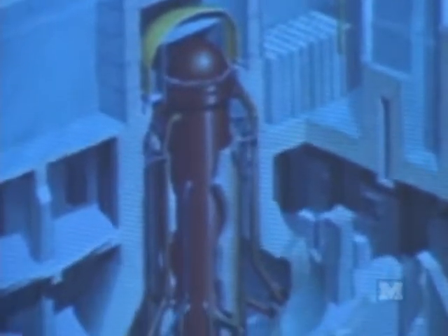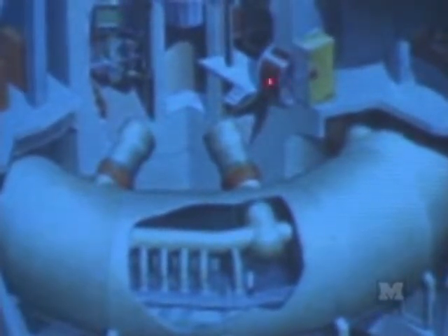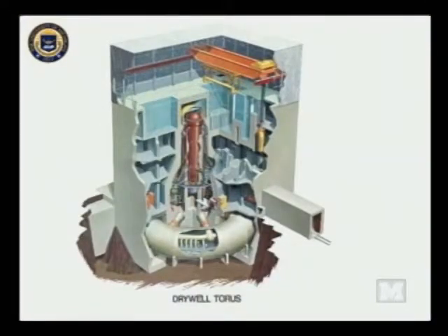And then connected to the light bulb-shaped dry well, the primary containment, is the suppression pool, which is connected through automatic depressurization system valves, several of them. The idea is when the pressure builds up in the reactor vessel, steam can be vented to the suppression pool, thereby relieving the pressure. And of course, the suppression pool itself will be cooled by another heat transfer loop, and the water will be pumped into a reservoir, which I'll indicate in the next slide or two.